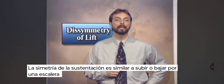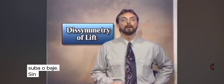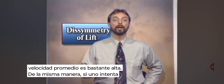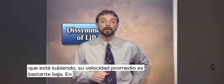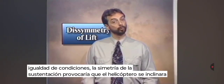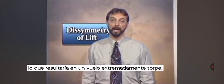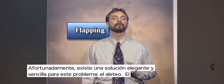Dissymmetry of lift is sort of like riding an escalator. If you just stand there, you go the same speed whether riding up or down. But if you walk up the escalator or advance while it's moving up, your average speed is pretty fast. By the same token though, if you try to walk down or retreat on an escalator that's moving up, your average speed is pretty slow. All things being equal, dissymmetry of lift would cause the helicopter to roll in the direction of the retreating or left side of the rotor disc when in forward motion. This would make for extremely awkward flying. Fortunately, there's an elegant yet simple cure for this problem. It's called flapping.